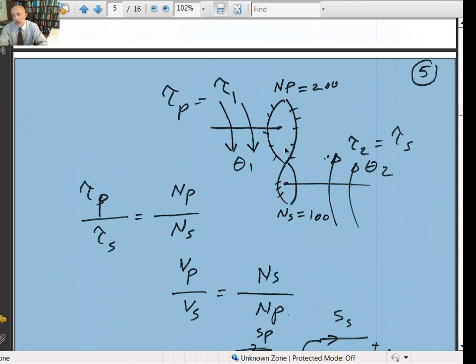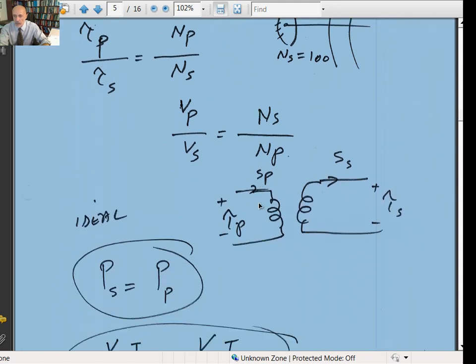So if you gear down, when the speed goes up, the torque will go down, and vice versa. When the speed is lower, when you go to a lower gear, then the torque will go up, but the speed will go down. So the speed acts like a current in a regular transformer, and torque acts like a voltage in a regular transformer.